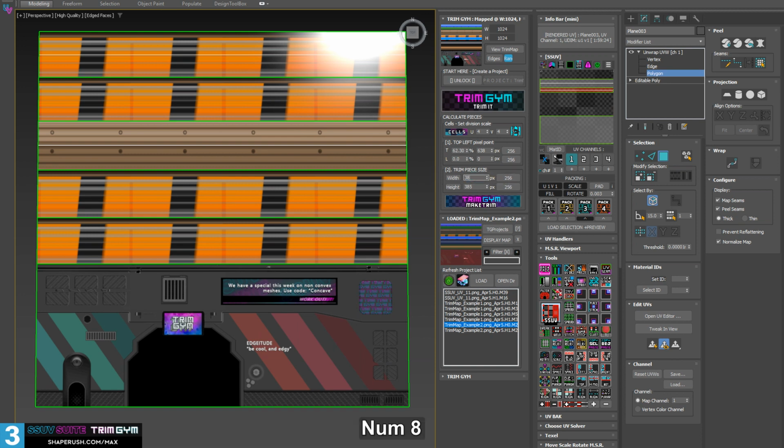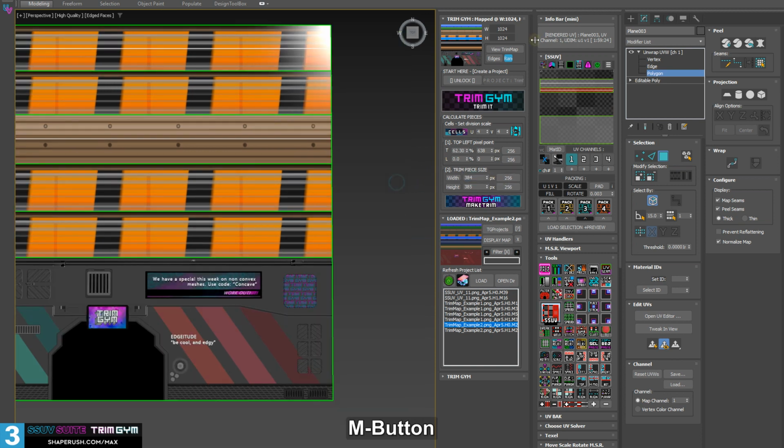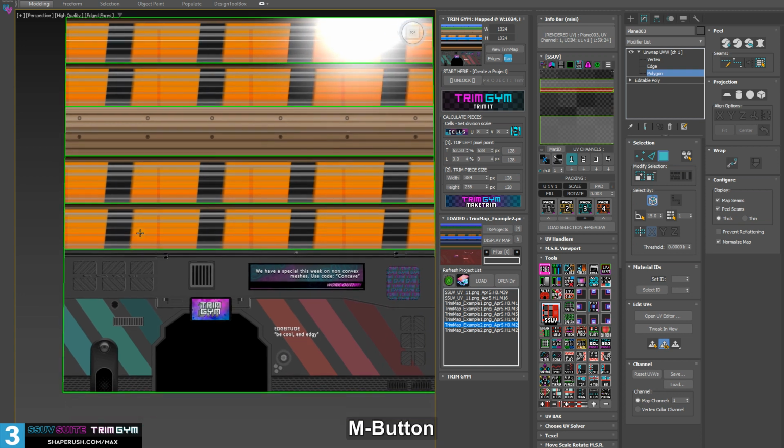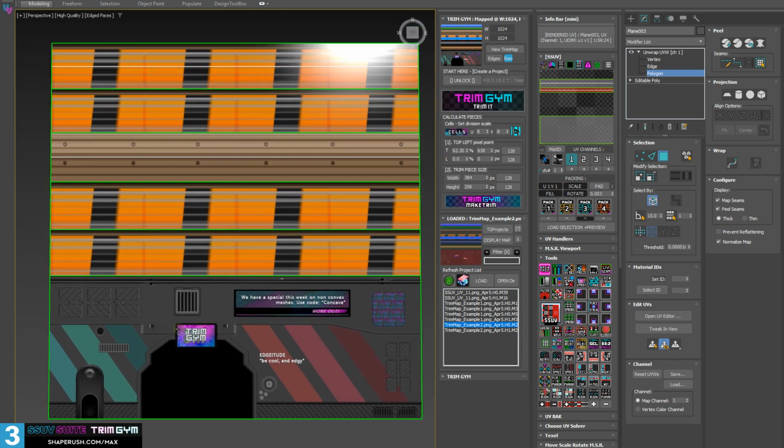I can't get there unless I change the cell division. And you'll see here that the 1024 is divided by the cell division to create these step increment numbers. So left click decreases, right click increases. Okay, so the width is going to be 384, the height is going to be 256, and I need to set the position here for where that's going to begin, and I believe that's going to be, I don't know, let's just set it at like 240, I suppose.